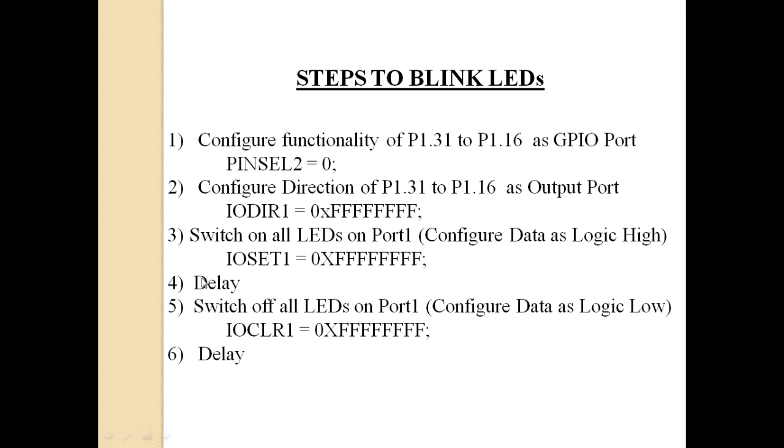So this delay you can write using any for loop or any loop statement. In this program you will be giving only some arbitrary delay. You are not generating an actual 500 millisecond delay. Some delay you are generating. So you will be making the LED on, you will generate a delay. That means that the LED will be on for that much time. Then you are making the LED off. Again you are giving the delay. So the LED will be off for that much amount of time.